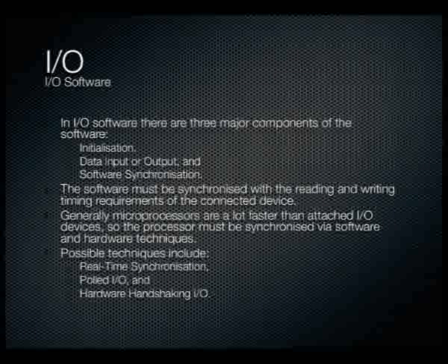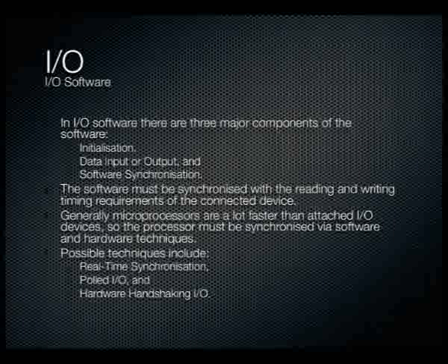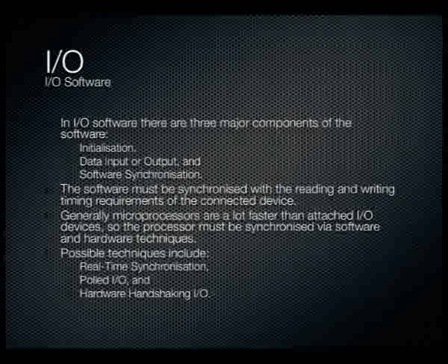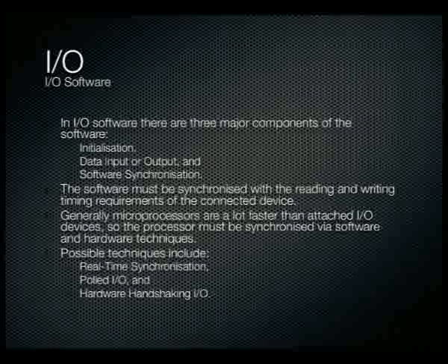Generally microprocessors are a lot faster than attached input-output devices, so the processor must be synchronized via software and hardware techniques. Possible techniques include real-time synchronization, polled I/O, and hardware handshaking I/O. And I'm going to go through a few of these examples.